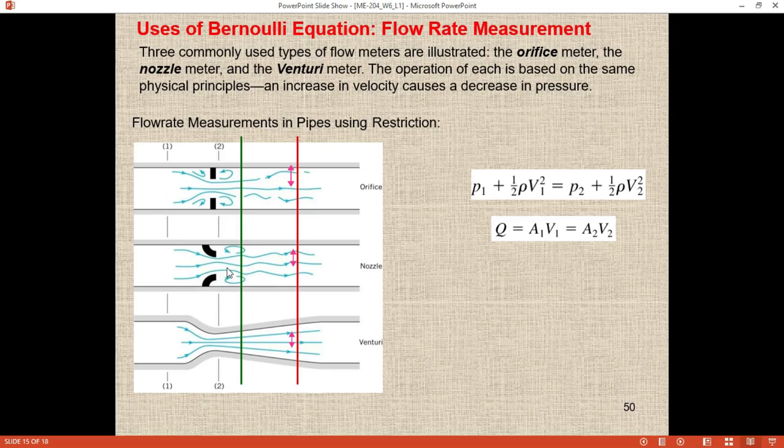If you take the nozzle section, you can see that in the orifice the fluid layers are separated from each other. Here the distance is less, here it is very much more, here it is something else. It's very turbulent and abrupt in the orifice. But in the nozzle, it seems a little organized, but even then some portions are vaporized and there is a cavitation effect. If you insert any pressure measuring device, you will not get an appropriate reading.